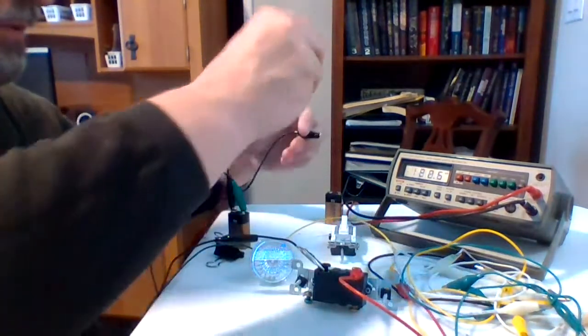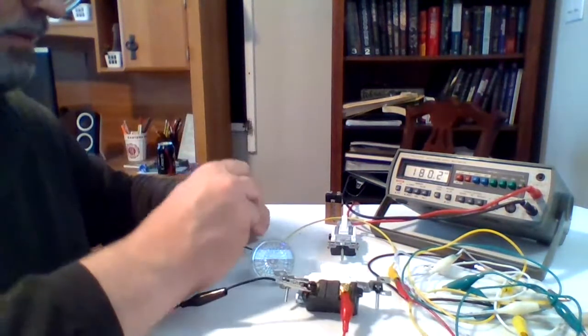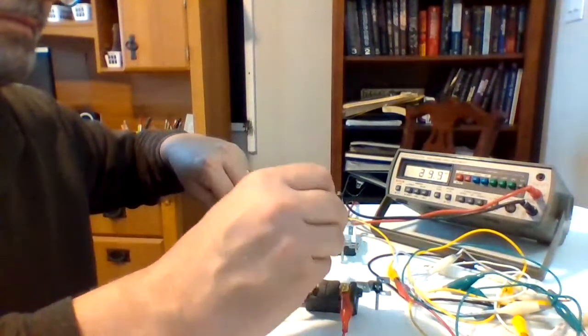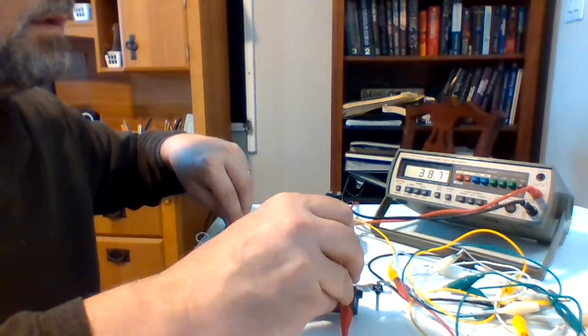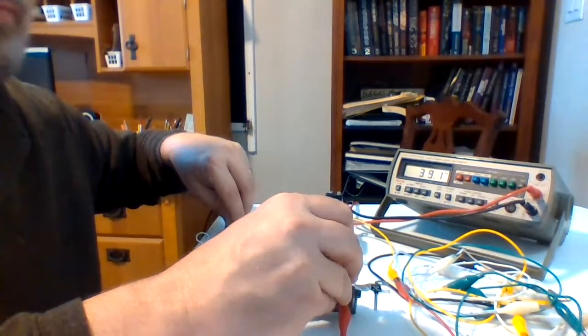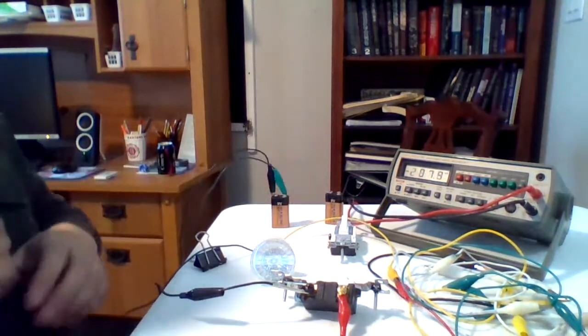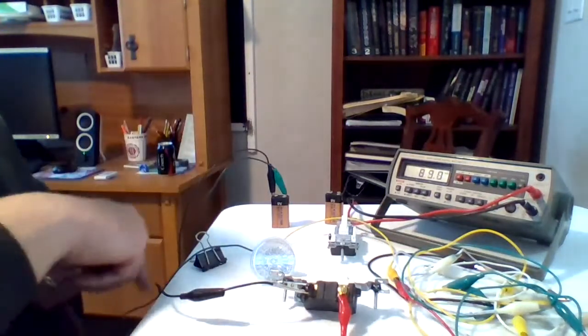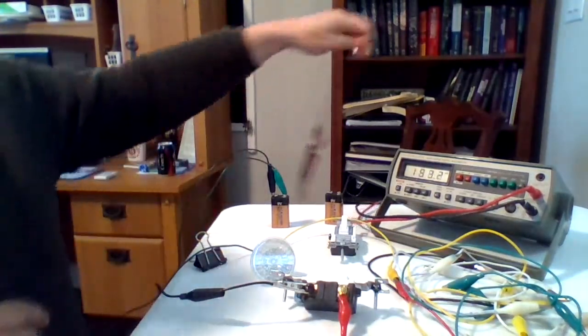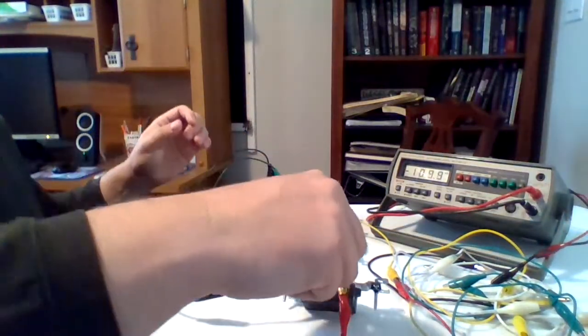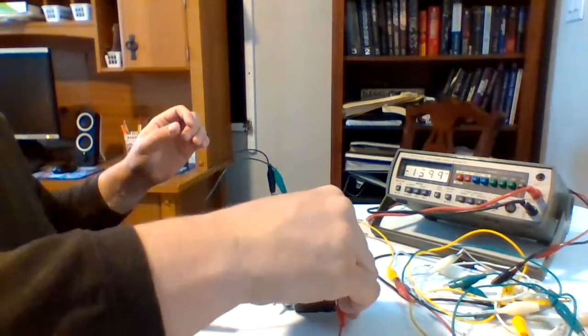So what this tells me is that the reason this light isn't on is because this switch is not operating. Because if I measure the voltage from here to here, it's 44 millivolts or virtually none. So that tells me there is no voltage being lost from here through this light through there, so there's no current going through there. And more importantly, there's no voltage difference. The voltage difference is here. And now when I flip this switch, that light's going to turn on.